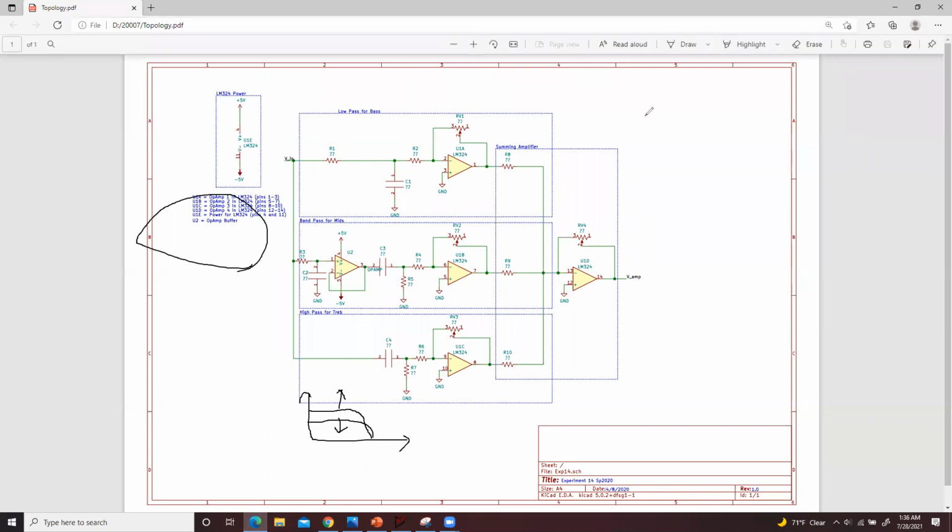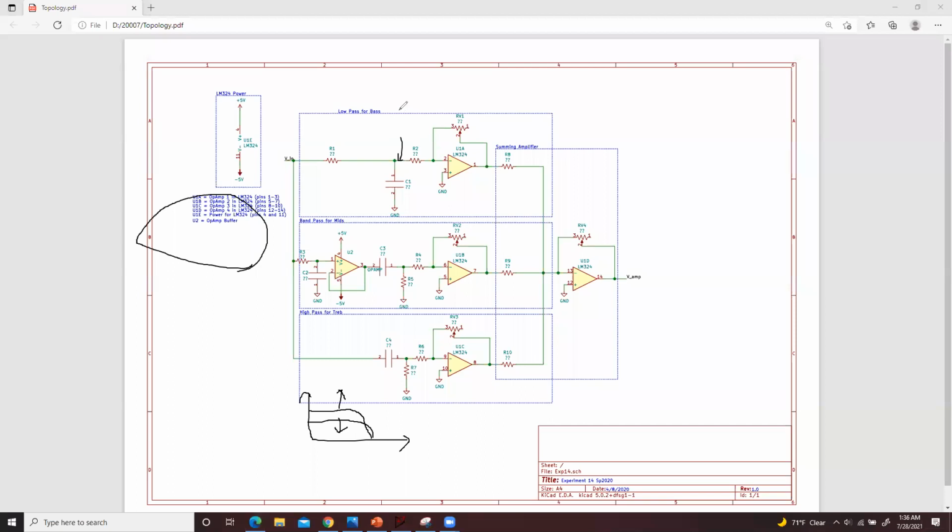So before R2, you put a buffer. Remember the buffer is something that looks like this. I think you learned this in lab 8 or lab 10. In the pre-lab, you built the buffer. Remember the buffer helps you to separate the circuit, and then this should also work. So if you don't want to change the value for R1 or R2, you can put a buffer in between.